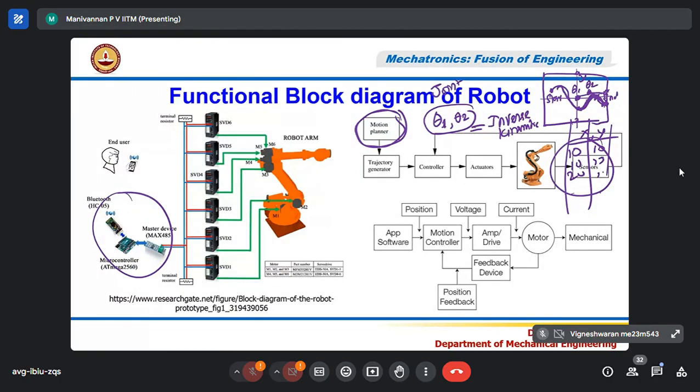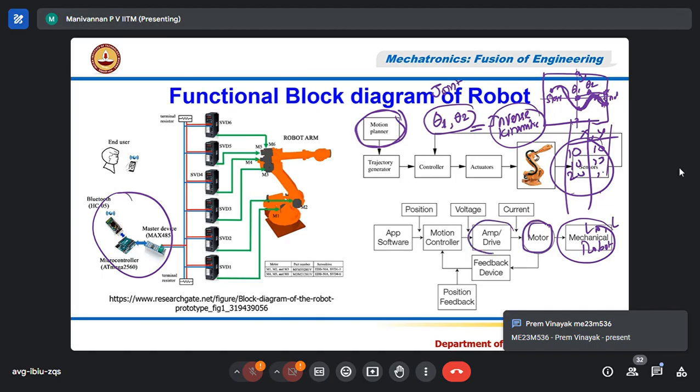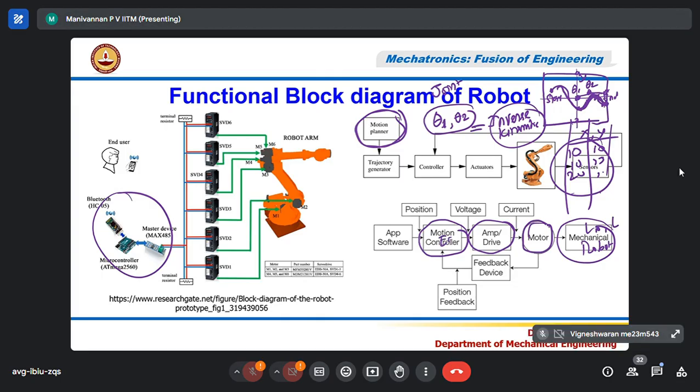So that is called the inverse kinematic model. So you may use forward and inverse kinematics, which run in the computer. This is the mechanical structure of the robot. I am talking about one kinematic path. One motor is there. It consists of L0, L1, and this is my motor, which needs to be controlled by a power amplifier, which in turn is controlled by the computer. Motion control is nothing but my ECU. If you give the end effector position, x comma y or x comma z in 3 dimensions, the software will compute theta 1, theta 2, and theta 3.